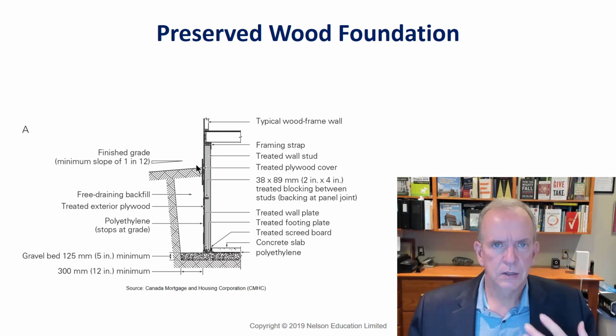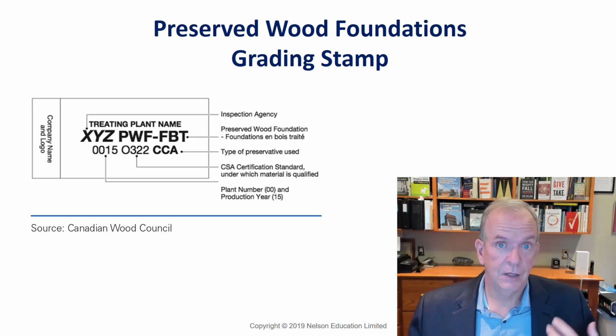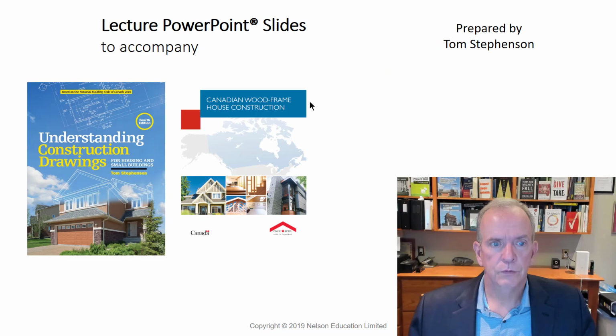But if you're building a house, there's probably this sort of resistance from purchasers. I've only seen 3 or 4 of them in Ontario. I see them more out west, but I don't think it's a growing industry for those reasons. They're easy to insulate, easy to finish in the basement. You have to have a sump pump in the basement and a gravel base, and the water flows to that, and then you pump it away. But those are some of the aspects of preserved wood foundations.